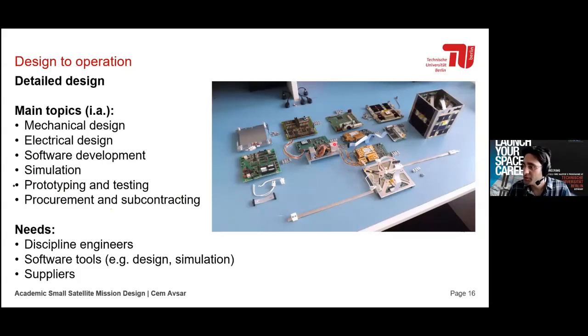You can see the reaction wheel assembly. Those are 3 wheels that are arranged perpendicular to each other. They rotate, and thus the satellite rotates in the opposite direction. Then you have the top plate here with the antennas that are released with a wire melting mechanism. You have the communication equipment, the GPS transceiver, so this is BZ4. Then you have the camera, the patch antenna, and so on and so forth.